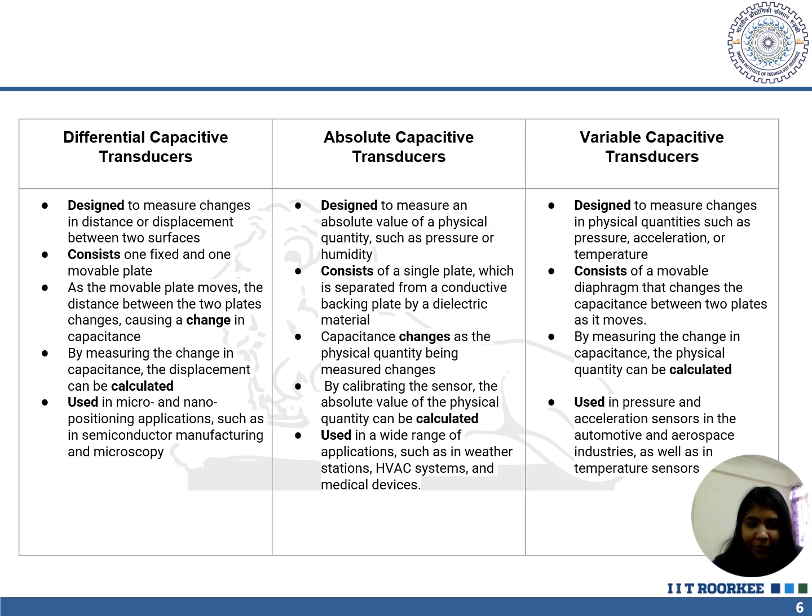So their operation is as follows. In the differential capacitive transducers, we can measure the change as the distance between the two plates changes. The same follows for the absolute capacitive transducers and the variable capacitive transducers. So by measuring the change in the capacitance, the displacement or the physical phenomenon that we were measuring can be determined.